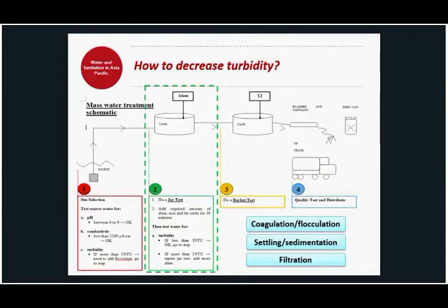Sedimentation on its own can take time, or in the case of very small particles, they will remain suspended. So silt and clay particles can remain suspended almost indefinitely. So sometimes we carry out coagulation-flocculation to enhance and speed up the sedimentation of particles. Filtration is another option of removing particles. In bulk water treatment, this is usually done with a sand filter or membrane filters, and these processes can be enhanced by also using coagulation and flocculation, so they can go together.